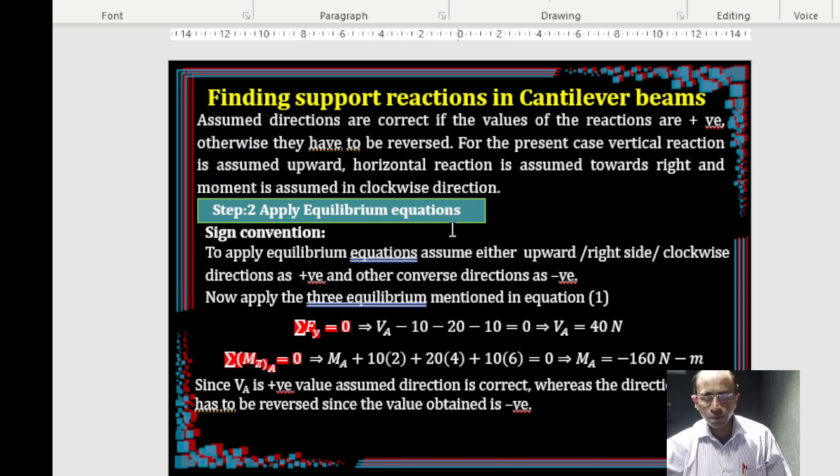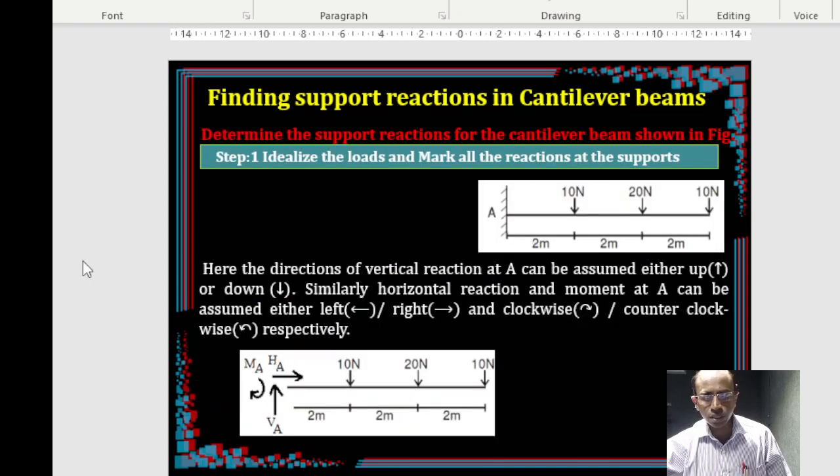So you can apply the equilibrium equation, right? While applying the equilibrium equations, you should look at the given problem. As long as there is no inclined loading system or horizontal loads acting on it, the Fx equation has no significance at all. That's why in beams most of the time the loading is vertical, and we don't use the sigma Fx equation, something around 95% of the time. Only when inclined loads or some kind of horizontal loads are placed on the beam can we refer to the sigma Fx equation.